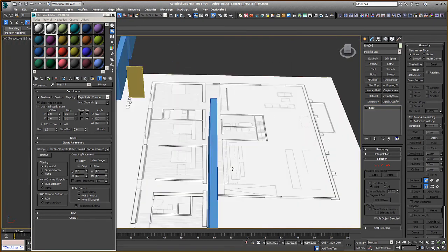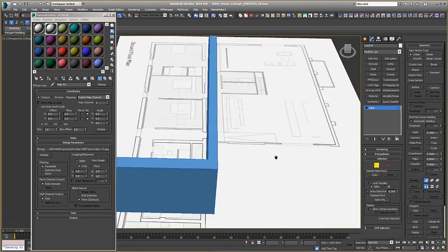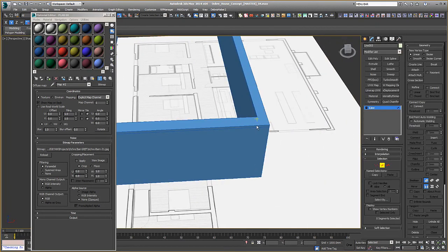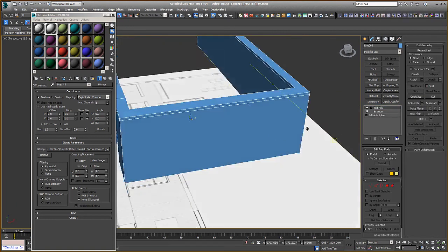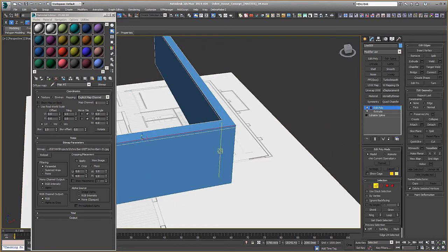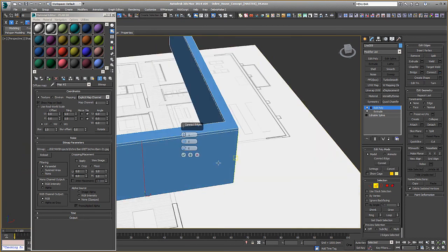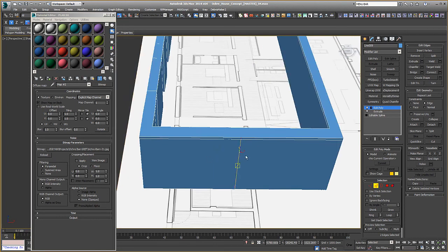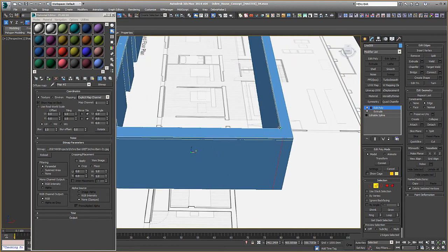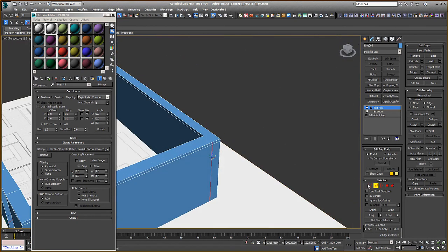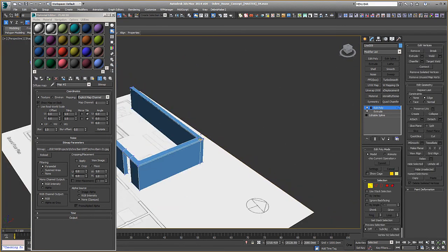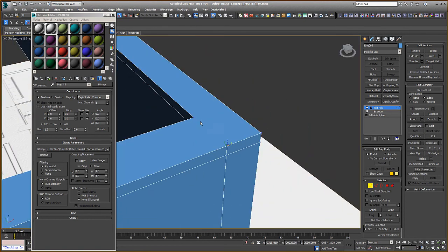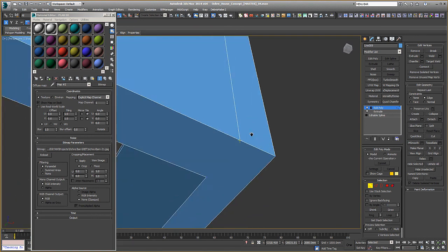what we need to do is cut some geometry through here. So we'll select this, and we can connect that just once, and we can set this to edge constraint, which allows us to move along the edge but still snap in the X value to there. And now I can select my vertices and connect these verts.